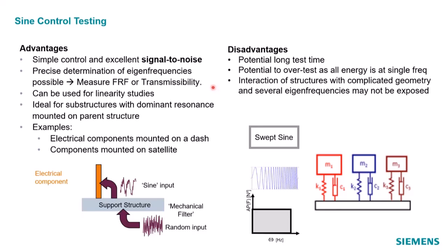If you're measuring just accelerations, you can use the phase information and that good signal to noise ratio to calculate some good quality transmissibility functions, which have phase information. So we can use those for operation deflection shapes, or as input to classical modal analysis, or for operational modal analysis also.